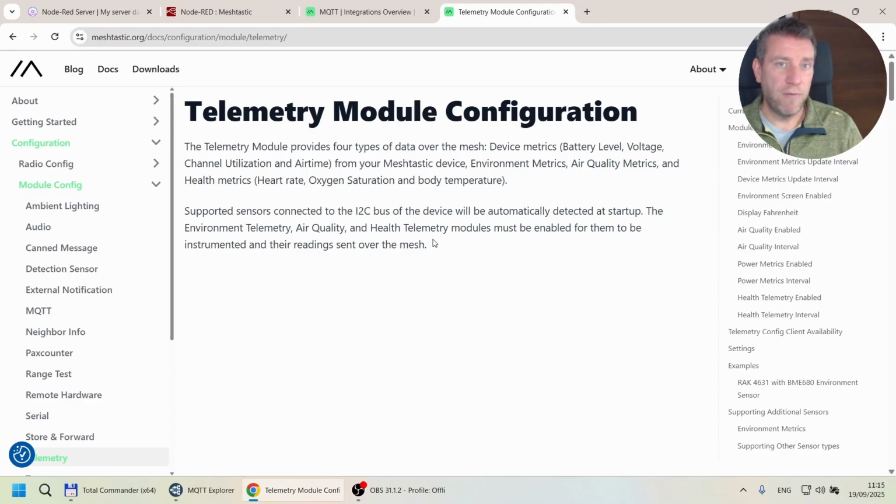So for example, you have an ESP32 which runs Meshtastic. You have another Atmega or any Arduino board which is reading the sensor, and it sends the sensor data to the ESP node, but that message is getting sent as a text message, like somebody typed in the temperature, the humidity. That can be any sensors, any number of sensors, and then you can format the data you want, and then you send the actual reading as a text message.